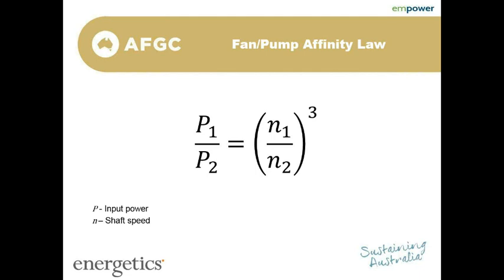So that's really what's driving the energy savings. And I'll run through some examples and explain that a bit further as we go. I'll just mention also that this is for the variable torque loads. This equation and the calculations don't necessarily apply for constant torque loads, which is when you might need to slow the shaft speed, but you still need that same level of force, or rotating force or torque, and so it's proportional to the power. Those are things like conveyor motors, reciprocating pumps, or compressors.